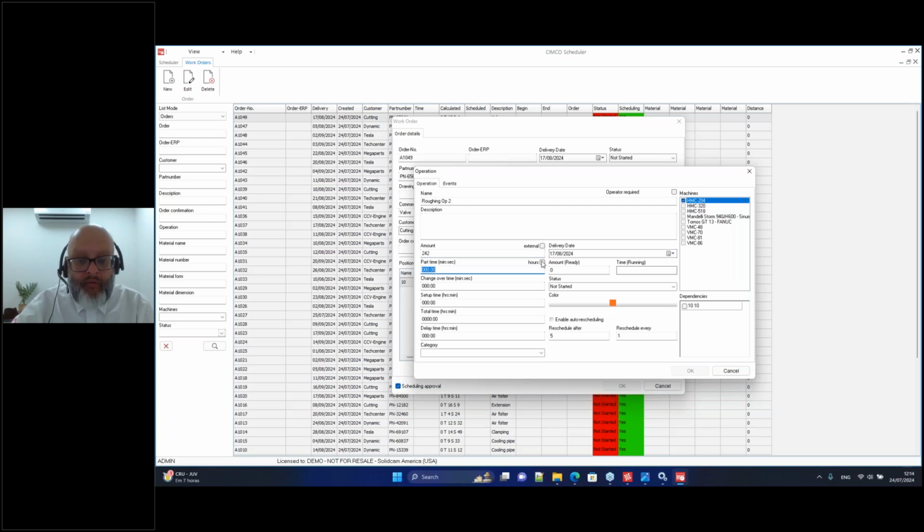It takes, you can choose, 2 hours and 15 minutes to manufacture this part. Change over time, the time you need to change the parts. Setup time is 2 hours. And total machining time for this is 530 hours. And if this part needs to sit for a few hours before you can move it to the next machine or the next operation, I'm going to say it's going to be sitting on the floor for 4 hours before I can do this. And what happens is that I can say I also depend on this previous operation to be completed so I can start this operation.